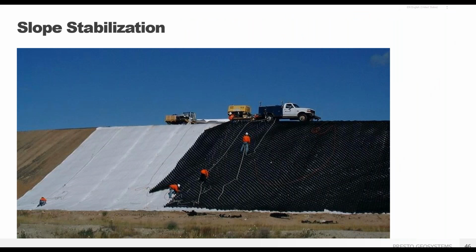Here's an example of a railway slope project in Montana with the use of ATRA anchor stakes. Aggregate infill was chosen for both sides of the embankment for erosion control, plus a low maintenance slope cover. This project shows the benefit of material delivery at the top of the slope, greatly reducing the handling and truck traffic into surrounding areas. When such delivery from the top is possible, it makes for a faster, safer, and easier installation.